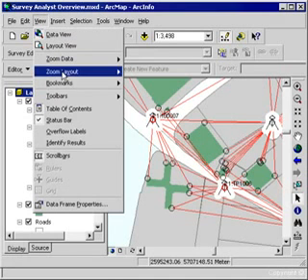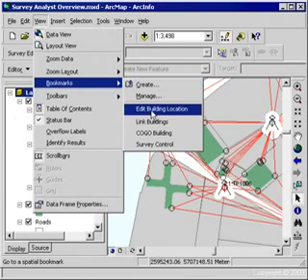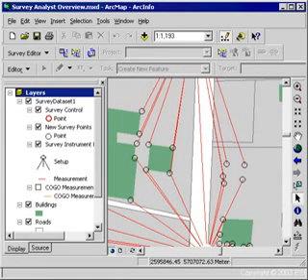I'm going to go to one of my bookmarks called edit buildings, and I want to edit 2 buildings using that survey data. You see 2 buildings represented. This green building, you see the 4 corners identified as survey points. Those survey points were computed within Survey Analyst based on the measurements that were loaded from those instrument setups. And you can see where the survey points fall within a certain distance of the corners of that building. You'll also notice on the right-hand side the location of a building that's been surveyed but is not in my GIS layer. I'm going to perform 2 types of edits here on these buildings.